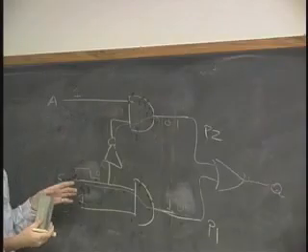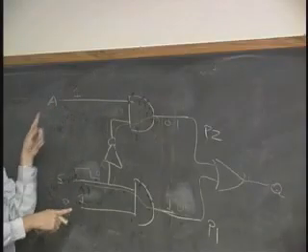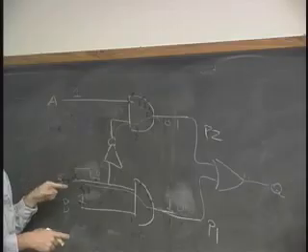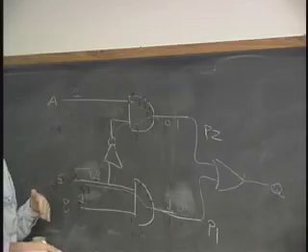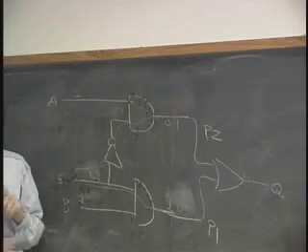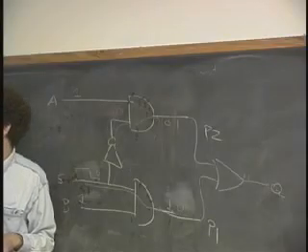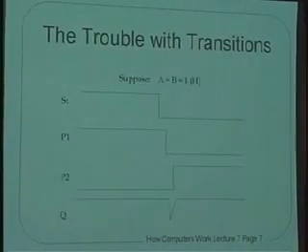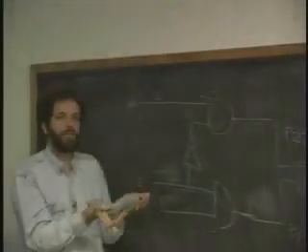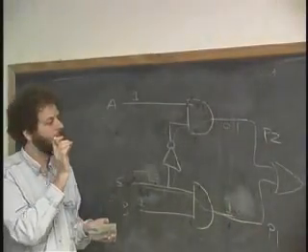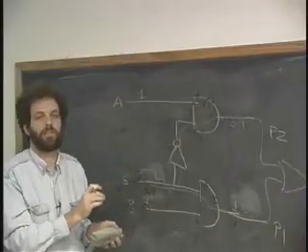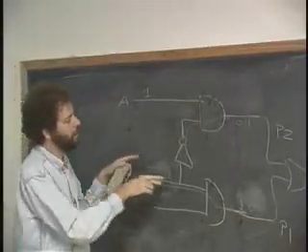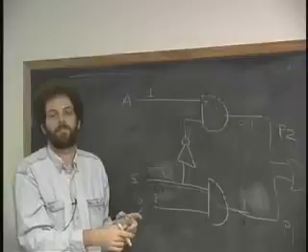And so a selector given 2 inputs, A and B, both of which are high, which is told first, choose B, and then next, choose A, may go through a transition where Q, which you see over there on the board, goes from high to low and then back to high again very, very quickly, as the internal circuitry of who's in charge of holding this output up goes through what's called a timing race, okay? There's a race between turning this guy off and turning this one back on.